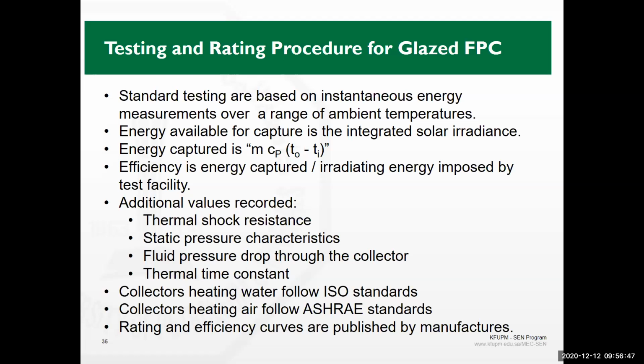Collectors with very thin tubes might need higher pumping power because the friction is higher. Bigger tubes, lower pumping power. So you should be aware of this. How much is the fluid pressure drop as it passes through the collector? How much is the thermal time constant? How long will it take before it starts heating the collector up to a certain temperature?